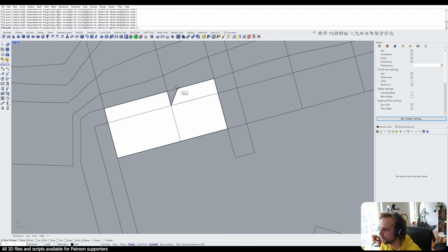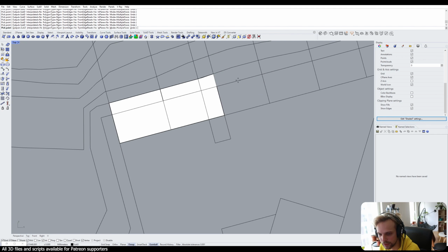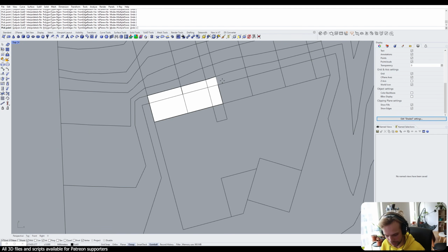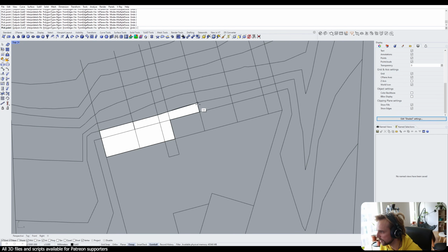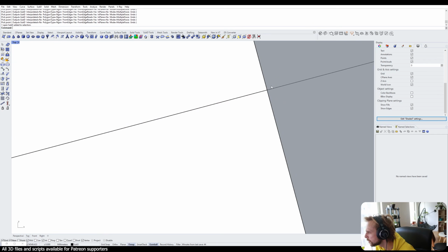So you can always use this append command to quickly create polygons that are already joined. Well, except here, for some reason it's not joined. I can tell by seeing the bold line right here that it's not joined. We will investigate that in just a second. But for now, I'm just going to quickly go through this and create myself a starting grid. Just like that.